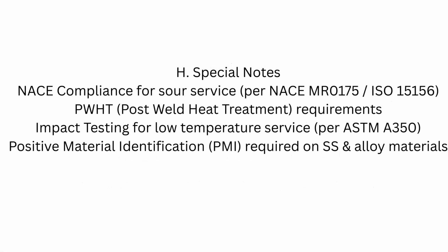Special notes. NACE compliance for sour service per NACE MR0175, ISO 15156. Post-weld heat treatment requirements. Impact testing for low temperature service per ASTM A350. Positive material identification, PMI, required on SS and alloy materials.